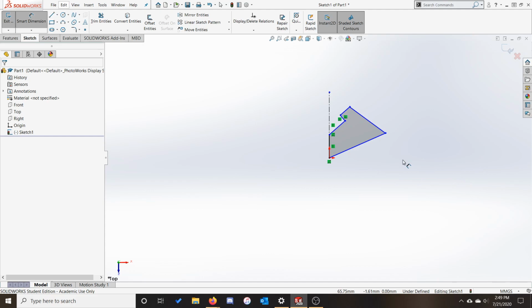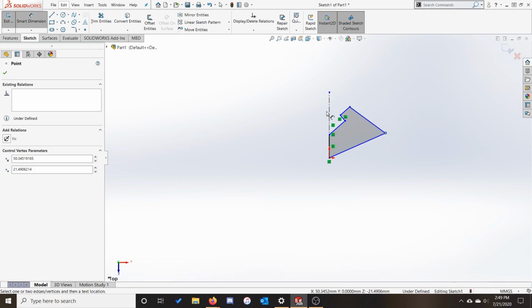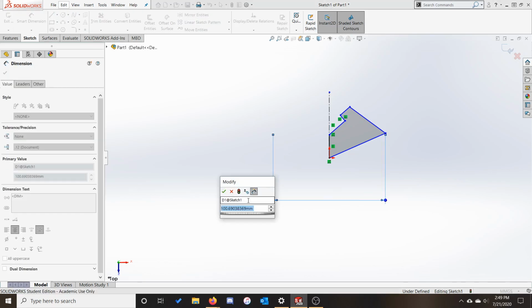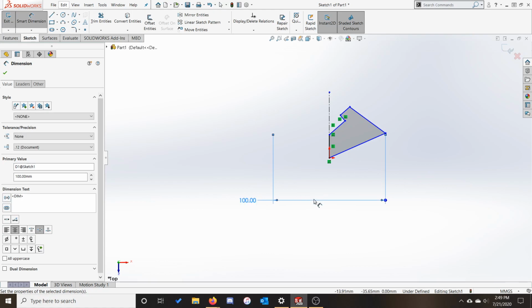When working within a revolve sketch, you can dimension from a known entity on the profile to the edge of our axis of revolution, and then move our cursor to the opposite side of the axis. This allows us to dimension a diameter value when we can only see a radial value, and is going to save you plenty of points on homework assignments throughout the quarter.